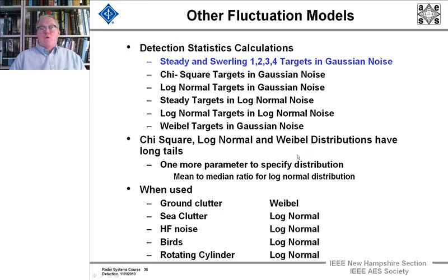And the main point, though, is find out how your target and your noise fluctuate. Most of the time, if it's a target that you can beat down with signal processing, you want to beat it down to Gaussian noise and then deal with it. You can't deal with the target fluctuations except to change frequency. But most of the time you're going to be dealing with Gaussian noise.